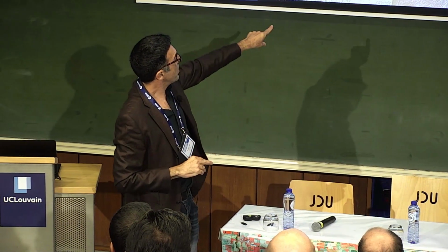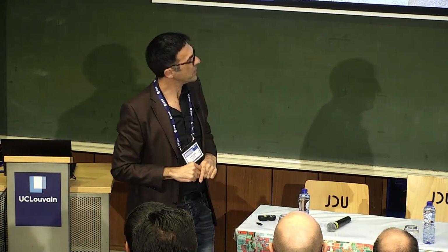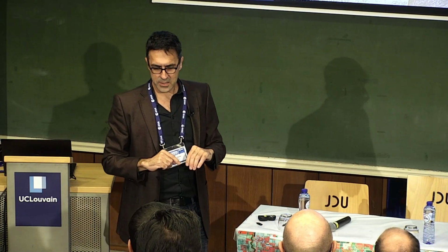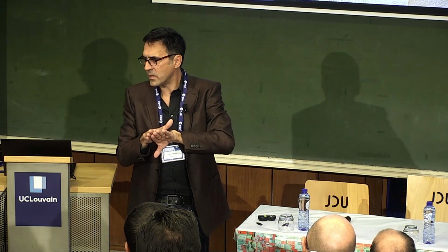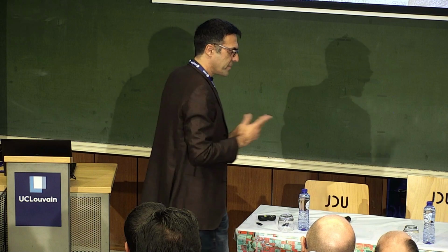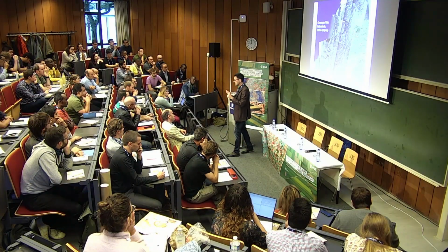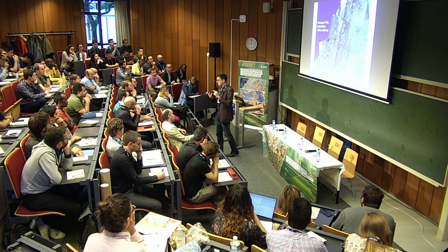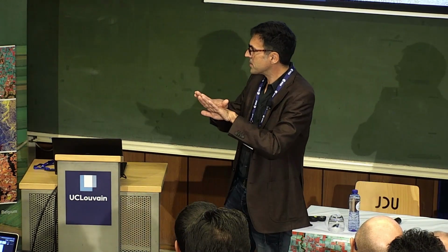And for example, where we are here, we're just southeast of Brussels. It means that these images overlap about 50%, right? So that means that the revisit time, which started with 12 days for 1 satellite, 6 days for 2 satellites, 3 days for ascending and descending, now gets back to, let's say, typically 1.5 days for overlapping tracks.